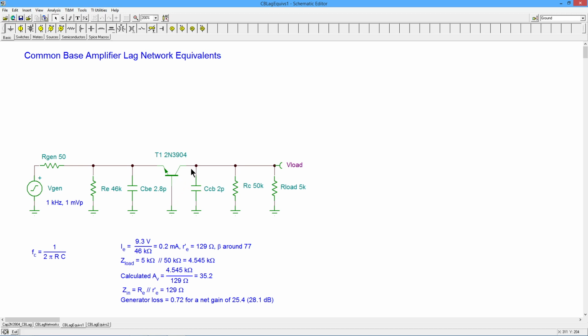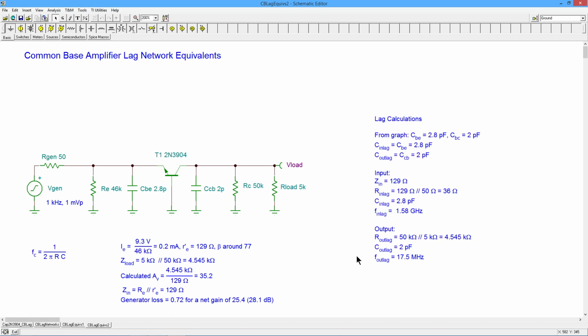The other resistance we have out here is the internal resistance of the IC current source. But given these values, I've got a 5K out here, which is really going to be the dominating element. That's big enough to ignore. This internal value is probably hundreds of K ohms, if not more. So comparatively, we can just say, all right, we've got the 5K and the 50, and we'll call it. Now all I have to do is grind this through my standard critical frequency formula. Get that out, and here we go.